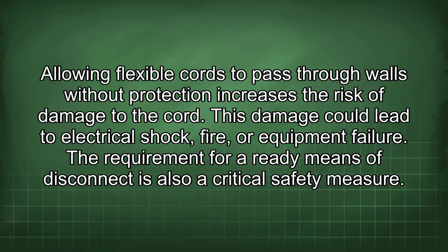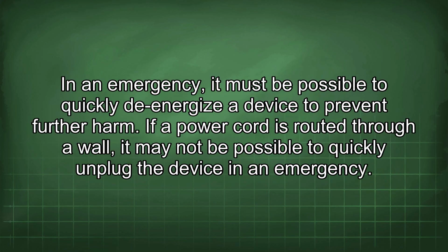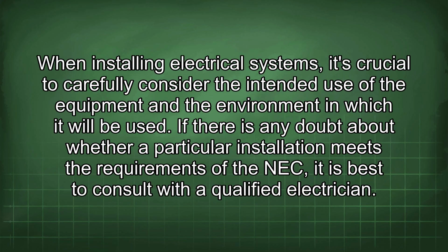The requirement for a ready means of disconnect is also a critical safety measure. In an emergency, it must be possible to quickly de-energize a device to prevent further harm. If a power cord is routed through a wall, it may not be possible to quickly unplug the device in an emergency. When installing electrical systems, it's crucial to carefully consider the intended use of the equipment and the environment in which it will be used.